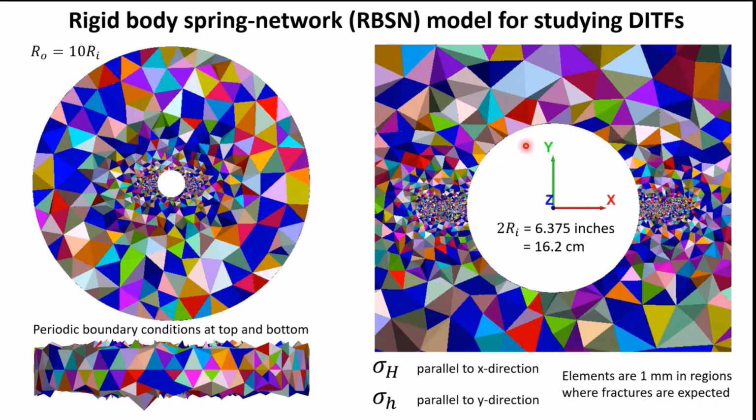Okay, so the crack usually, structure design and dam erosion all depend on the crack width, and these people usually want to analyze this crack in more detail. Well, I could imagine that you could design a rigid block model that looks at locations of cracking, and then ahead of the crack tip, you take the rigid block and you refine that. So you would have dynamic refinement during fracture propagation. I think that could be quite easily done.